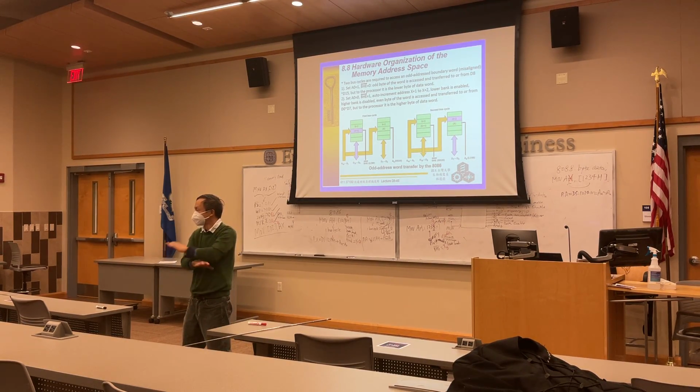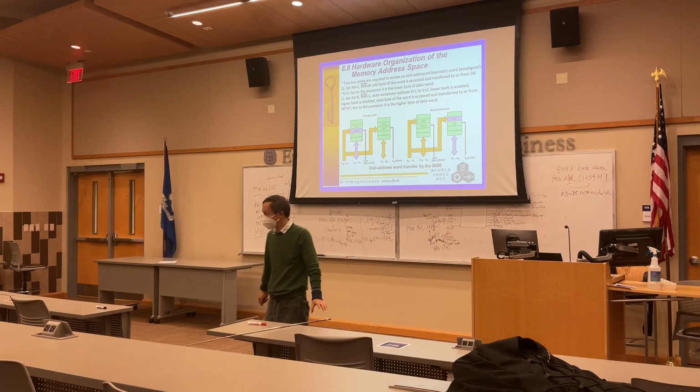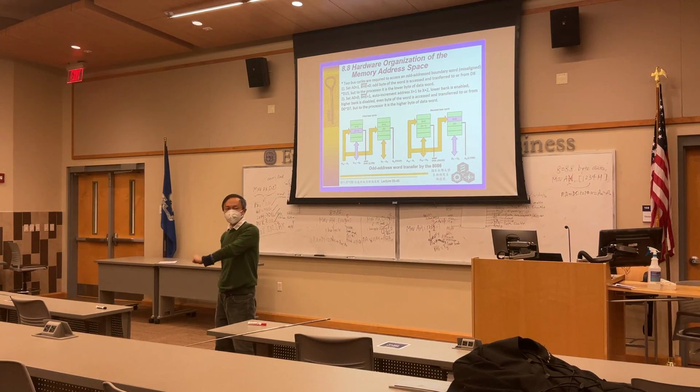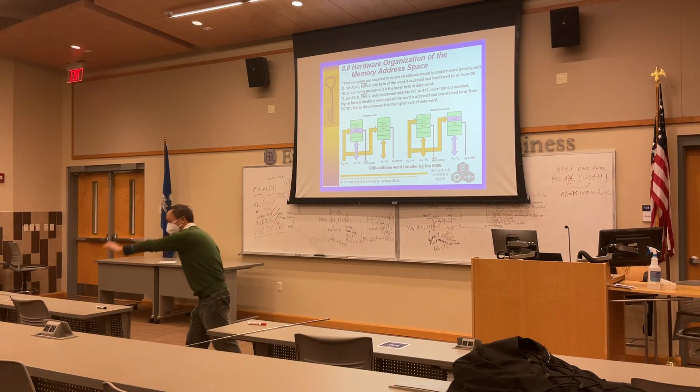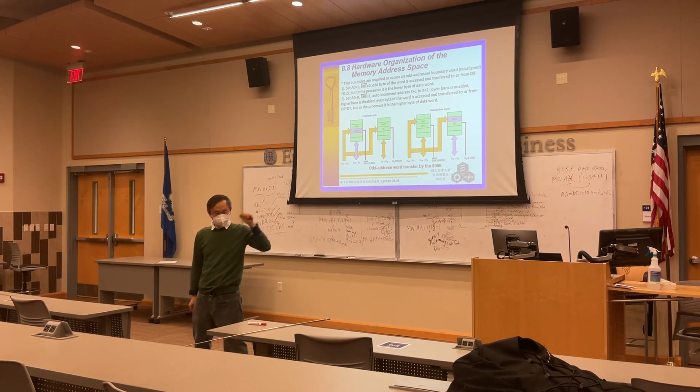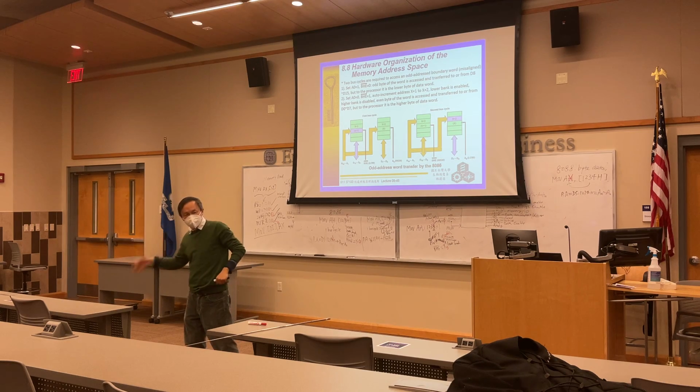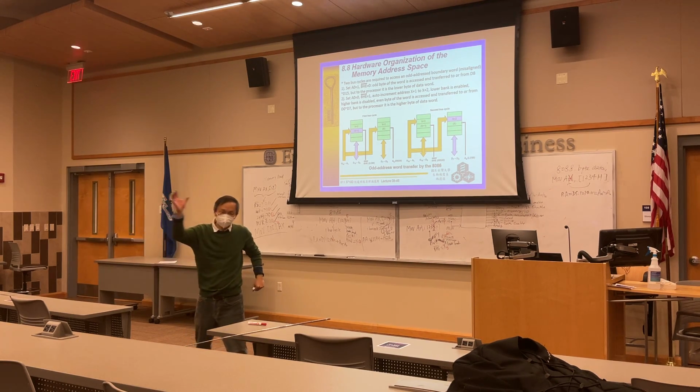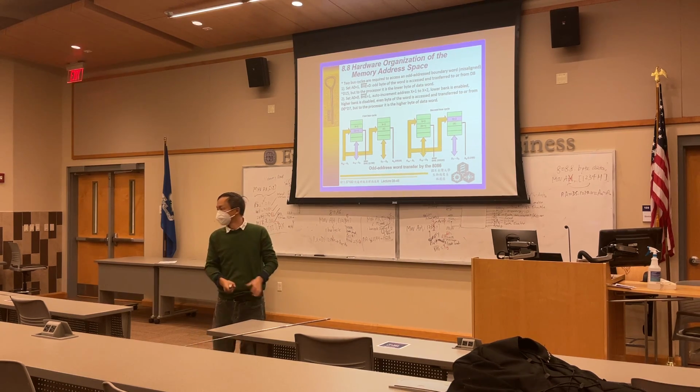No, because they are swapped. That's the reason we have to do two steps, two bus cycles. First, go to the lower byte, get it, send it on the high byte of the bus. Then increment the address, go to the next byte, and get it onto the data bus. Two bus cycles.